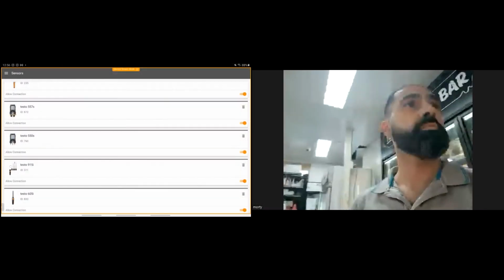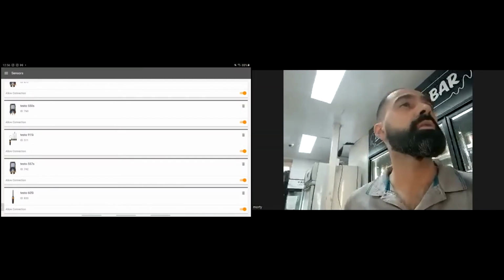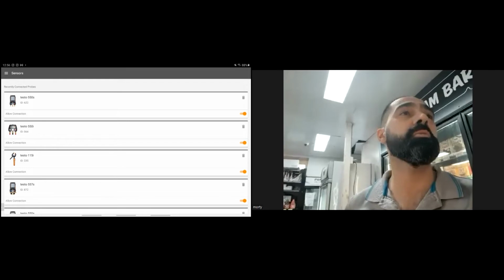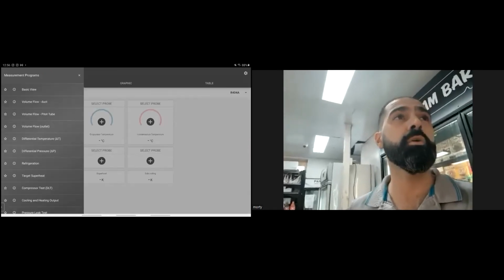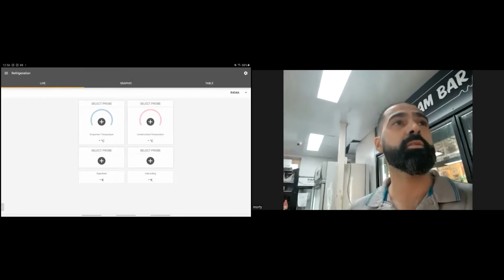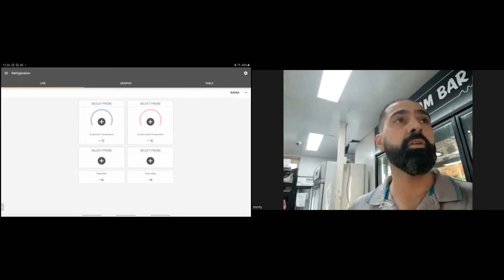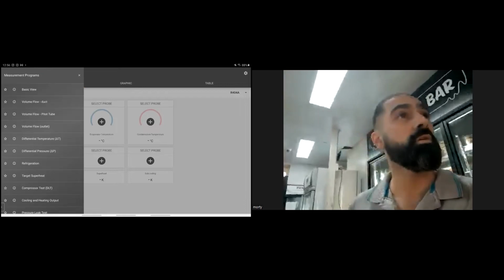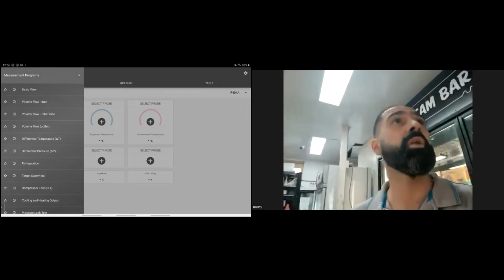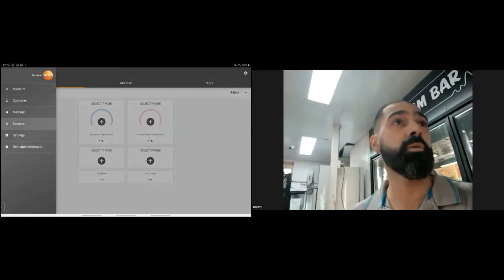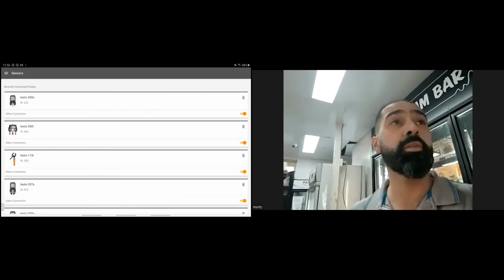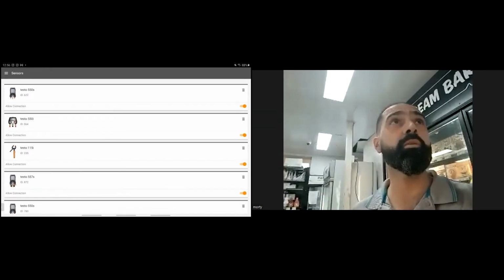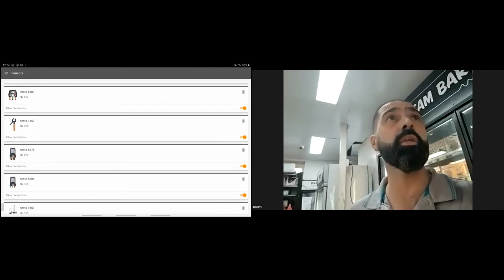Now the system has been stable. I'm looking at it right now, and it's giving me 4.7K superheat. My SST is minus 22. My exit temperature is at minus 17. Room temperature is 16. So this shows you've got 1 degree difference. Your bulb temperature is minus 17, which is 1 degree colder than the cabinet, meaning the system is actually doing work. It's pulling heat load out.